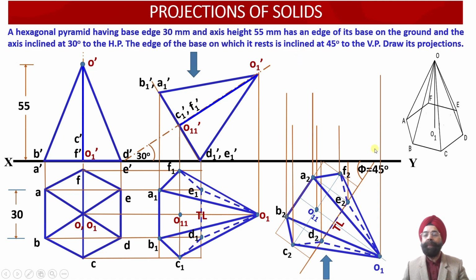And in the elevation projection view, from all the 8 points of the previous elevation projection view which we had drawn, we are going to draw the horizontal projector lines, and wherever we find the intersection points of the corresponding points, we obtain the elevation projection points over here.